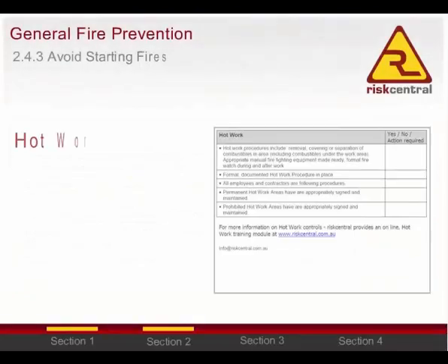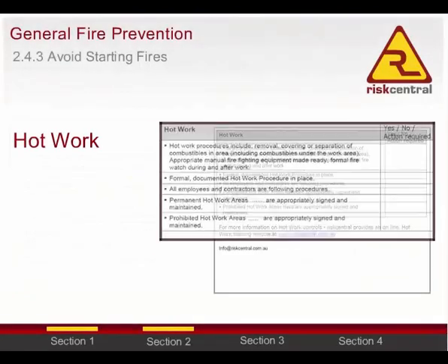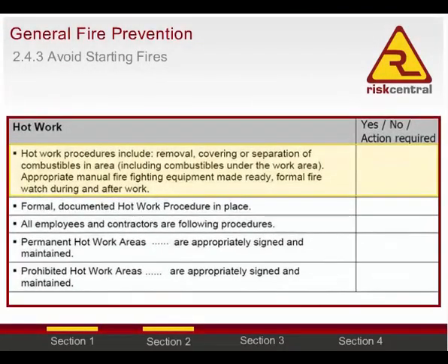Hot work. Hot work procedures include removal, covering or separation of combustibles in area, including combustibles under the work area. Appropriate manual firefighting equipment made ready, formal fire watch during and after work. Formal documented hot work procedure in place. All employees and contractors are following procedures.